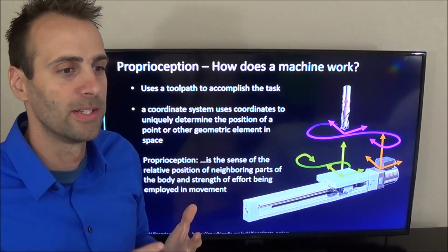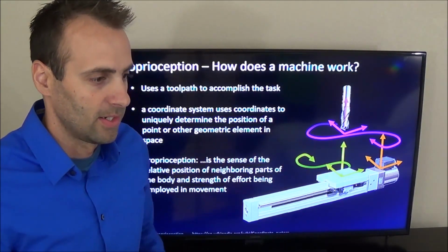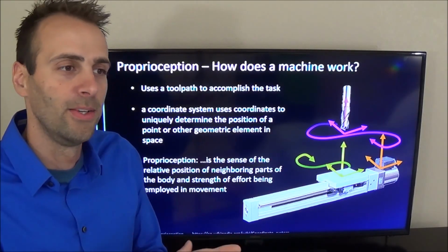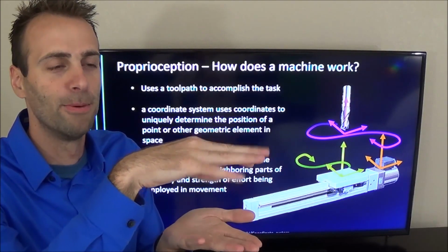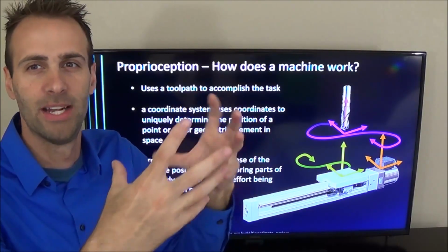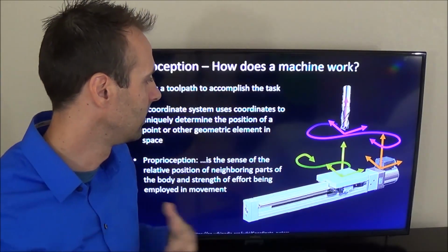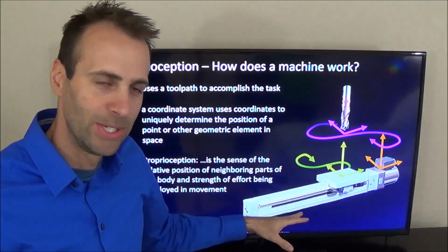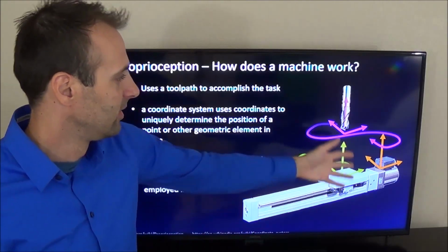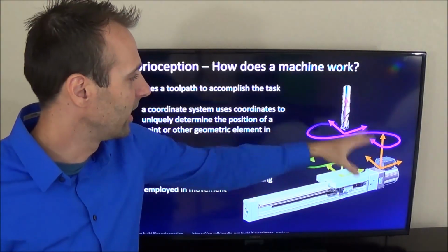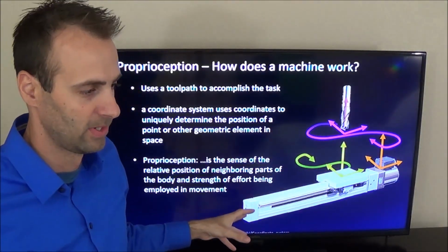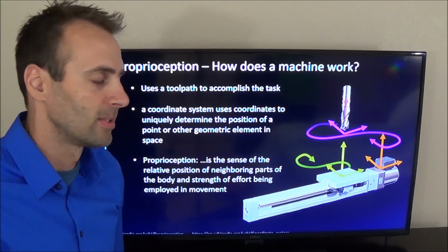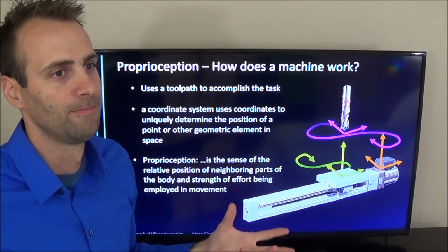It can be machine coordinates, it can be somewhere on the table. In fact, we'll talk about it later. I usually put mine 2 inches above the table because that's kind of the center of mass of most of the parts that we do. And then there's going to be a coordinate system on each machine element. And then, you know, you kind of need to keep track of all of these to make this thing happen. So back to the fundamentals, how does a machine tool work?